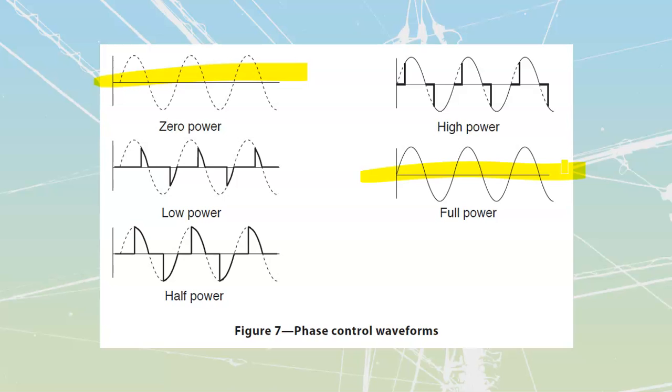If we want to do it with resistor control, we're going to be limited. Resistor control is really going to only allow us to go 50%. We can have it shut completely off, and then we can start to turn it on with resistor control, and we can get all the way up to here with resistor control, but that's going to be it. We can only do control from 0 to 90 degrees into that cycle.